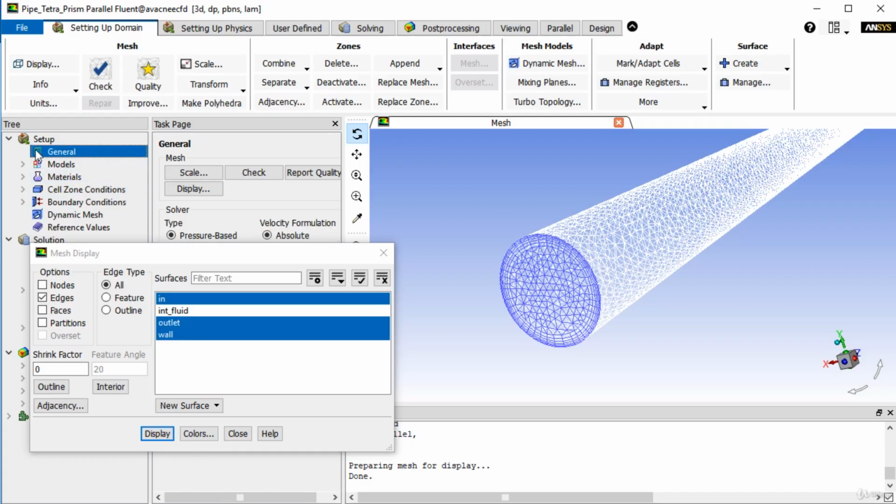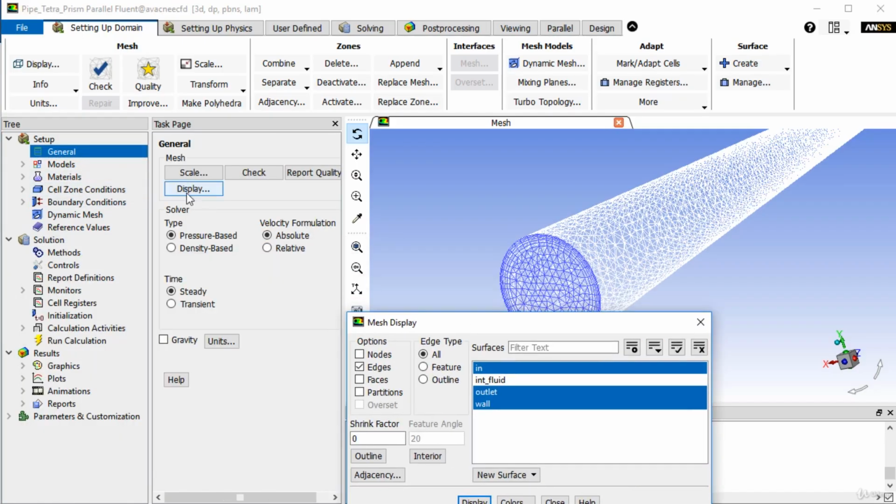And starting from the journal, you can see here that we have the pressure based solver. We keep this one for any flow which is incompressible, and we solve this case with the pressure based solver. For flows which have a Mach number greater than 0.6, or maybe more than 0.3, we go for compressible flow dynamics. In that case, we have to use the density based solver, which is well suited for these types of flows when the flow is compressible.